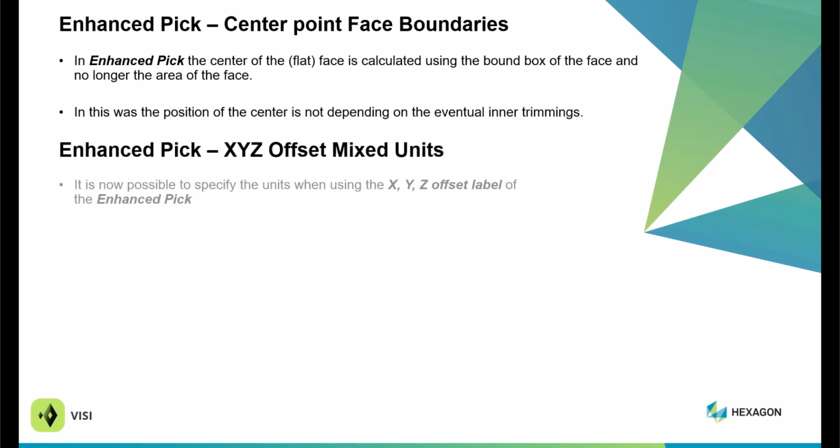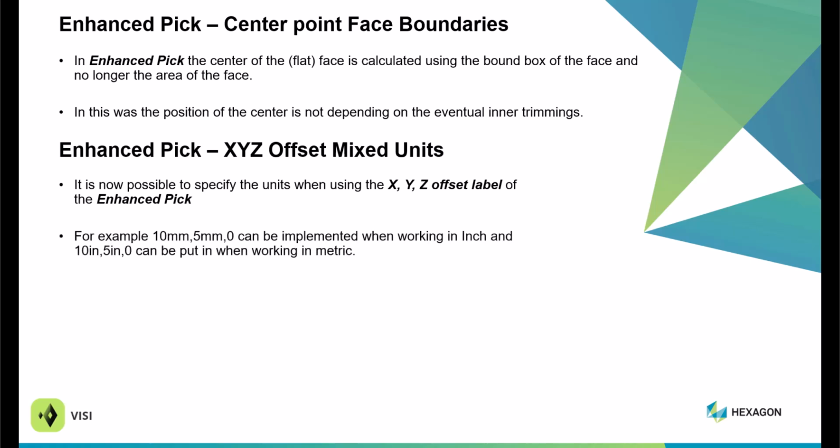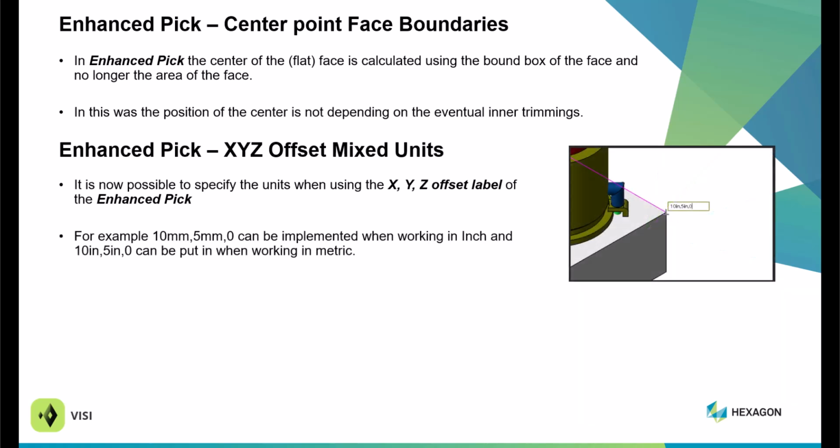When you're doing enhanced pick, the insert XYZ offsets, it's now possible to do mixed rendering inside of here. So when you're doing your insert XYZ offsets, you put an MM or an IN depending on the opposite unit of what you're currently in.